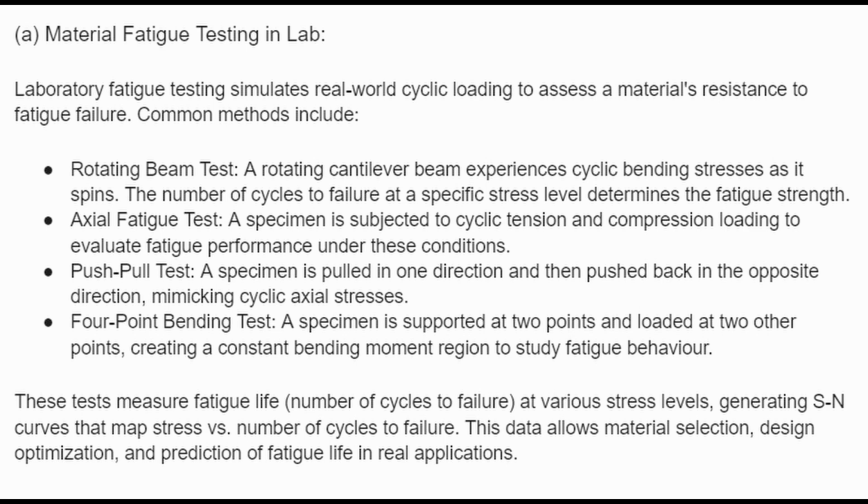fatigue behavior. These tests measure fatigue life, the number of cycles to failure, at various stress levels, generating S-N curves that map stress versus number of cycles to failure. This data allows material selection, design optimization, and prediction of fatigue life in real applications.